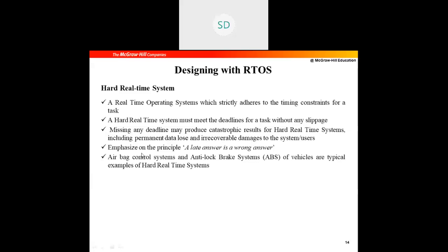So that emphasizes the principle that a late answer is nothing but a wrong answer, right? If you answer late in hard real time, it is a wrong answer. We cannot accept it. In soft real time, a late answer is fine. It is acceptable. Okay. So an airbag system is an example of hard real time. That is, whenever a crash occurs, within a second your airbag should open, right? If it doesn't open, then what happens? It definitely will affect the external environment, right?